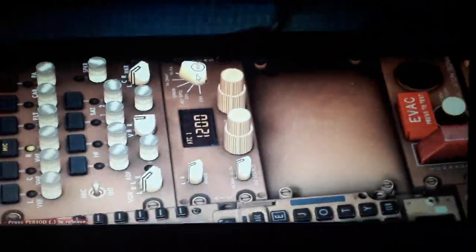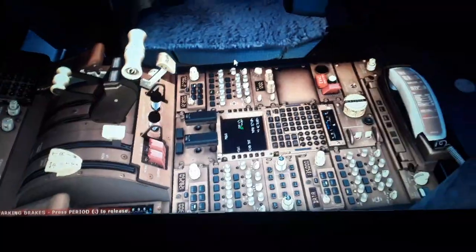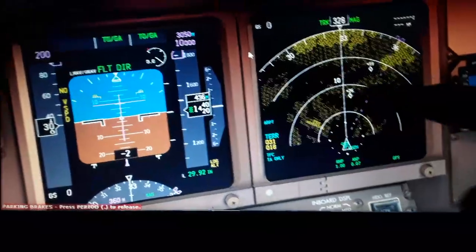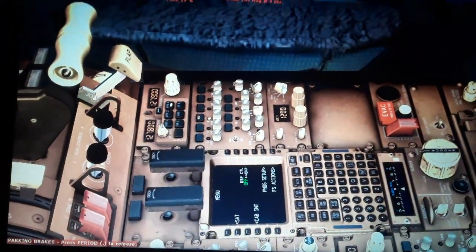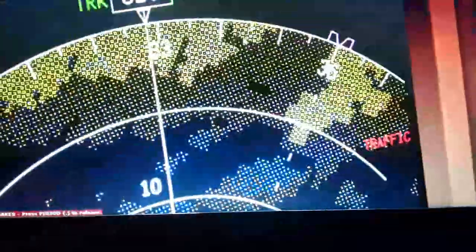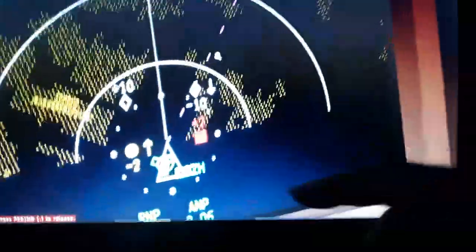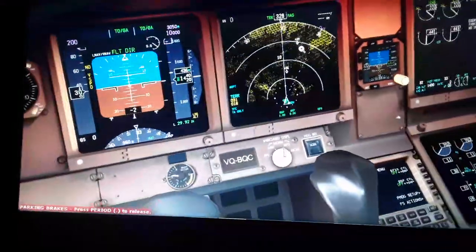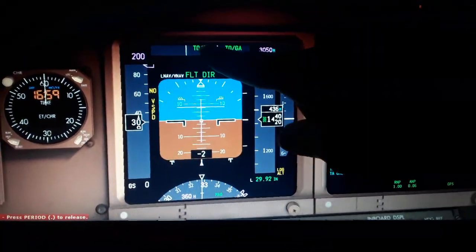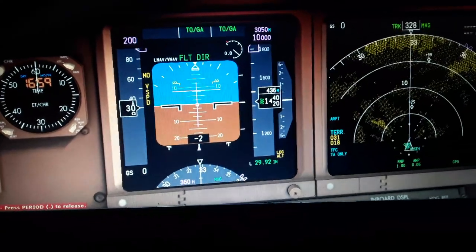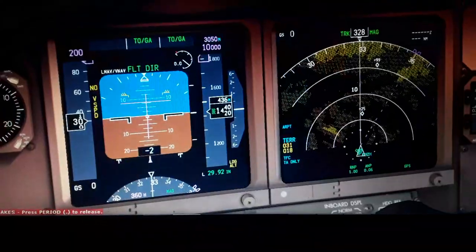You can test that. You have also the weather radar here for the terrain reflections. So you can see the traffic now displayed in the warnings. Some other aircraft. So let's do that again. Just one more time. We will see what happens. So we have the traffic. So we have the pitch ladder decrease, the bank angle decrease with the angle of attack of the aircraft, the flight mode annunciator, the autopilot and the autothrottle, later on vertical navigation modes.